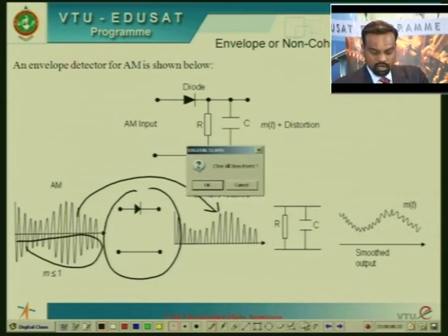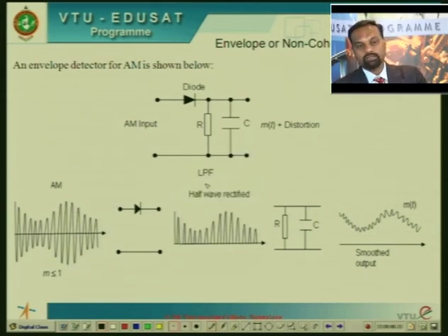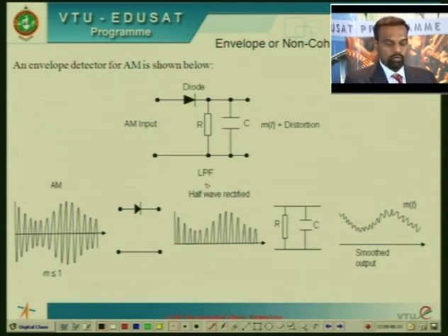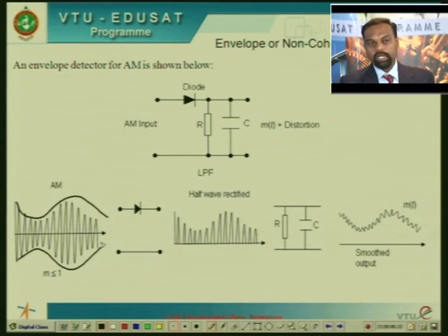So let us understand why this is very important for us. Since we are talking about a modulation index equal to 1 or less than 1, it is always going to be a double sideband signal, wherein you have one sideband on the top envelope and the other sideband on the bottom envelope. Since there are two sidebands available, it is more than enough for us to have only one sideband, and using that one sideband information, you can extract data from the incoming carrier signal.